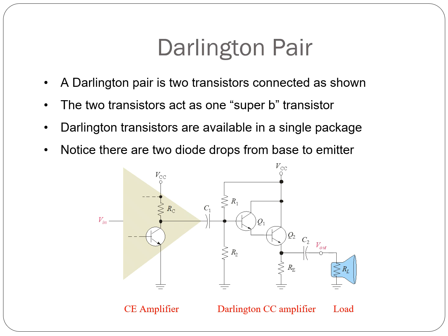And then if we look at the circuit, the left half is the classic common emitter amplifier providing voltage gain. The right side, the Darlington pair in a common collector configuration, provides enormous current gain to drive the load. And so here we see the load as a speaker.